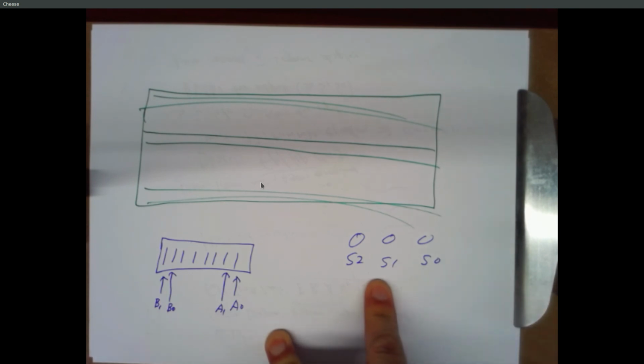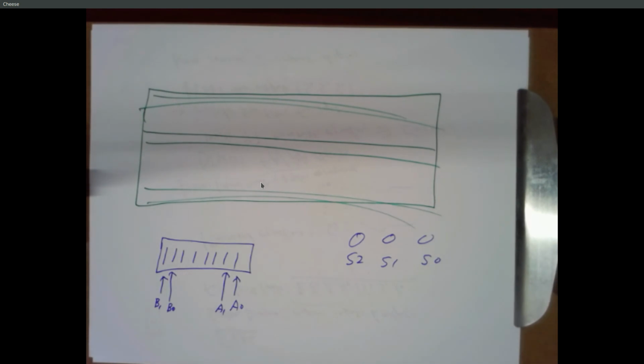Because I find students all the time doing this, and when we get down to it, their circuit's working perfectly, but they spent 2 hours trying to figure out what's wrong because they were interpreting the switches wrong or interpreting the LEDs wrong, right? So do it like this, right? Most significant bit to least significant, most to least, left to right. And keep B over here and A over here.